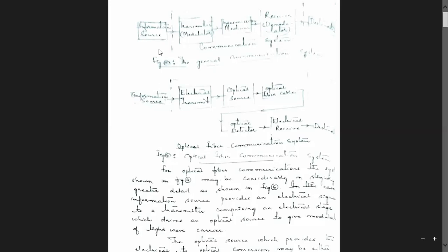At the receiving end, demodulation does the reverse operation and shifts the high frequencies back into low frequencies. The reason for doing modulation at the transmitting end and demodulation at the receiving end is that it is not possible to transmit low frequency signals far away. For that sake only, we do this conversion.